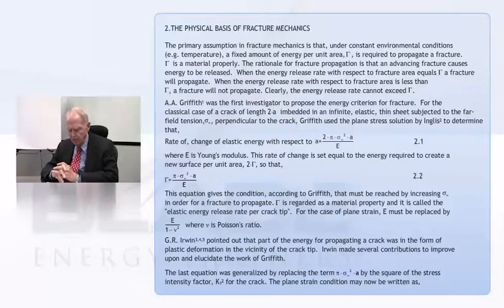He did his original studies on glass, and there were a couple of reasons for that. First of all, you can draw glass into very thin fibers, and when it's just been drawn, the surface is pretty much free of any flaws. If you let the fiber sit there, usually if there's any water in the atmosphere, it causes cracks to grow on the surface of the glass. You don't have to worry about the inside of the glass, because glass is amorphous, the hard way to say that it's not crystalline. So things don't happen on the inside, it's all a surface effect.